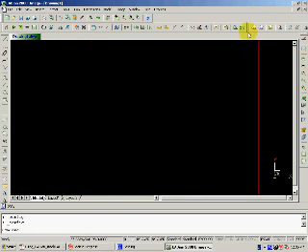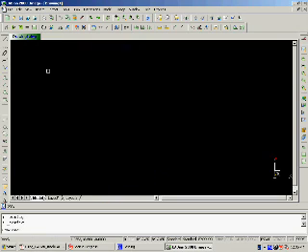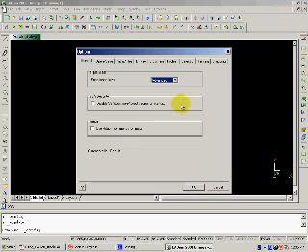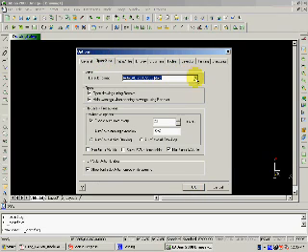Now, drag some toolbars around again. Look at some further options. Look at the formats. You can go all the way up to 2009. You've stayed at 2000 because you may have somebody that has an older version. You may want to back up your drawings every 20 minutes, as we just discussed there.